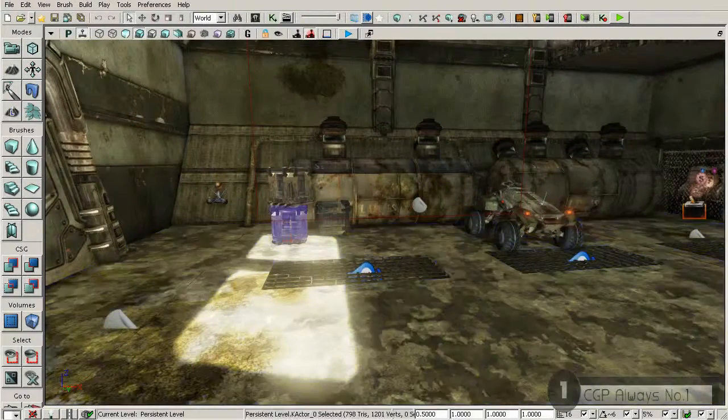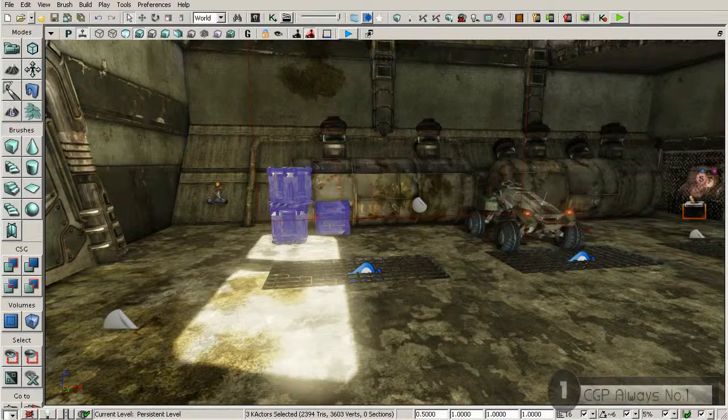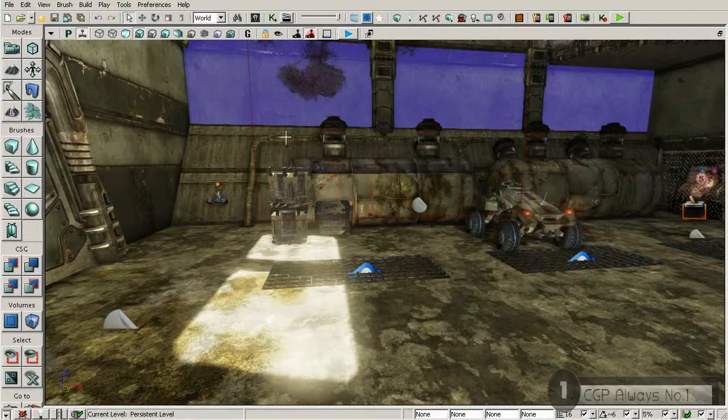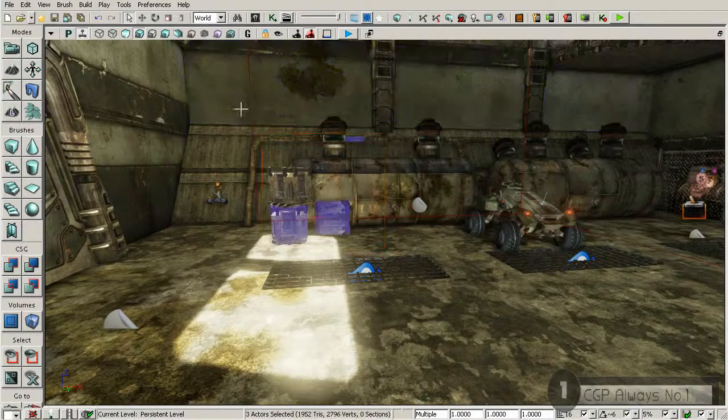You can select objects in the viewport by simply left-clicking on them. If you want to select multiple, you hold down Control and left-click. And remember, if you want to select multiple using marquee, you can simply hold down Control, Alt, and left mouse button, and anything that touches that window is now selected. Now, that's even if it's behind other objects, so you want to be careful with that, so that crossing or window selection becomes very helpful. So anything that is inside of that selection will only be selected here.